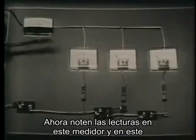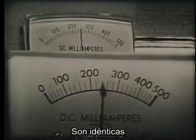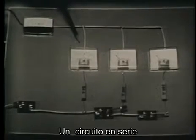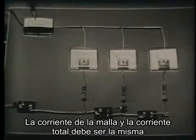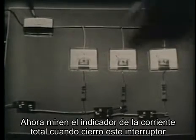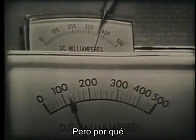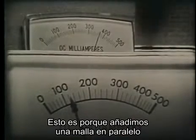Now, notice the readings on this meter and on this one. They're identical. Well, that shouldn't surprise anyone. We have one branch, a series circuit. So branch current and total current must be the same. Now, watch the total current indication when I close this switch down here. It increased. But why? This is because we added a parallel branch.